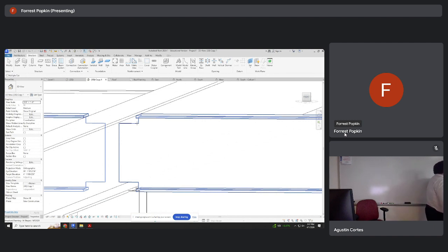Typically what's happening is I have my beams, and every so often those beams are going to support that decking, right? So if I have my girders up at a certain height and my beams at this height, what do you think is going to happen? It's going to be a mess. You want everything to be flush on the bottom of the corrugation so it has a level of support.